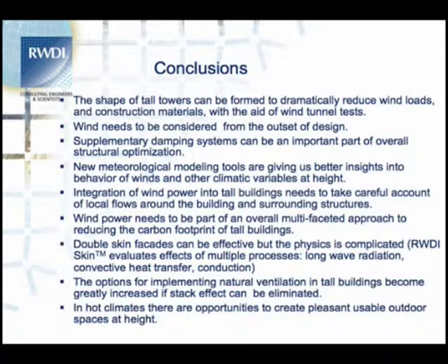Supplemental damping systems are an important part of the overall structural design, and should be treated like stiffness and mass as one other variable to help optimize the overall use of materials. New meteorological modeling tools are becoming very useful for giving us good insight as to what is the wind really doing up at 1 kilometer. Nearly all of the wind data that we have available, the vast majority of it is all recorded down at ground level, but there are balloon data at scattered locations, and the meteorological modeling tools that are used for weather forecasting actually do a pretty good job of modeling the whole of the lower atmosphere.